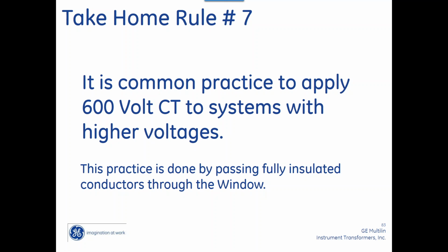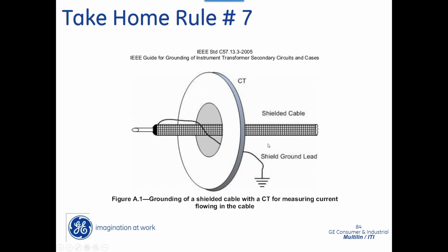So as long as you don't have a bare wire, you can use a 600 volt CT on a 5 kV application. And I'll show you some slides of how the manufacturers do that on switchgear, if I've got time.